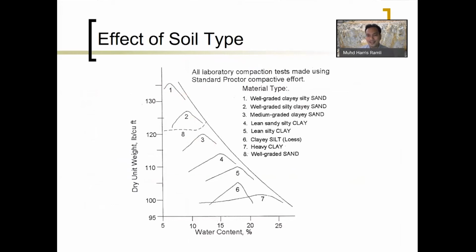Most of the time, the higher peak is actually sand compared to clay. So this is heavy clay. Sometimes when you compact clay, you will notice that it doesn't have that peak. It won't significantly have the normal compaction curve. So each and every time when you deal with clay, we usually go towards ground improvement techniques or soil stabilization techniques in order to increase its shear strength, compressibility and stability before you actually start doing any construction works. Ground improvement and soil stabilization is taught in fourth year if you are taking an elective